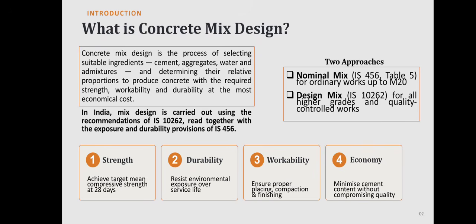And in India, mix design is carried out using the recommendations of IS 10262 and the exposure and durability provisions of IS 456. There are two approaches to be followed in the mix design. In the case of nominal mix, it is suitable for ordinary works up to M20. And design mix is suitable for all higher grades and quality controlled works.